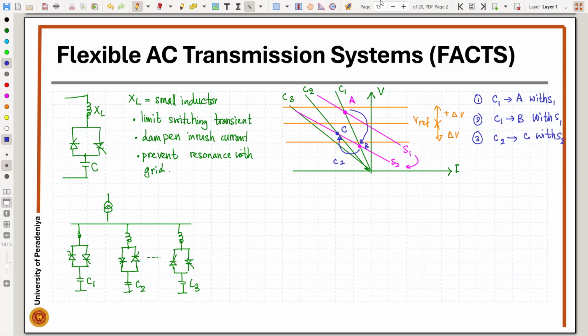Industry points, sir. Yeah, from the industrial point of view, what we want to get is the power factor improvement. So in that case, we will couple this continuously to the network. Am I correct? Yes, sir. Through contactors. Yeah, we don't control them on and off.